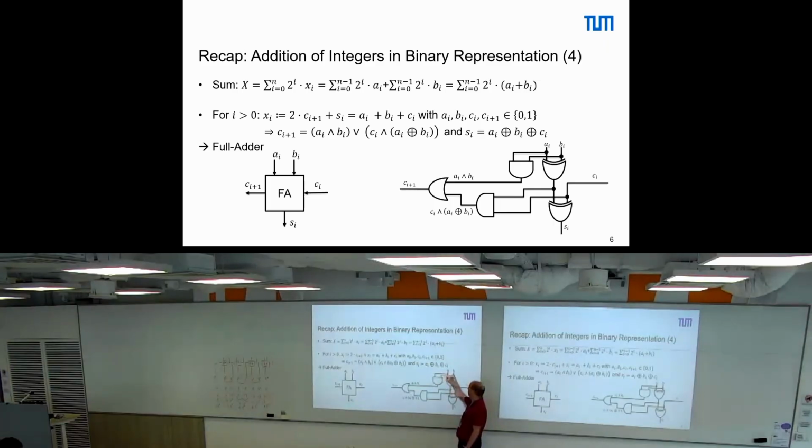Because we anyhow only add 1 for the LSB. This here becomes 0. The OR always forwards the signal from here, right? For most of the gates. Now, why is it better to have this? Obviously, if we opt out the AND and the OR gate, we reduce the area we have.